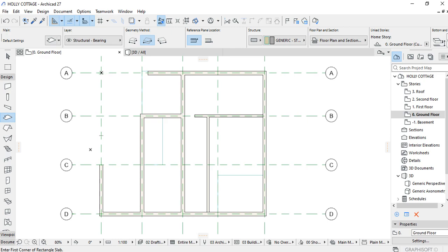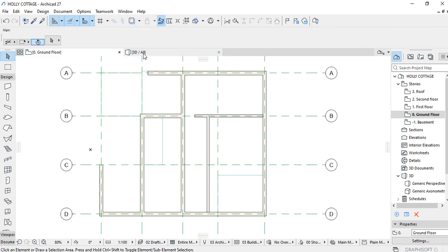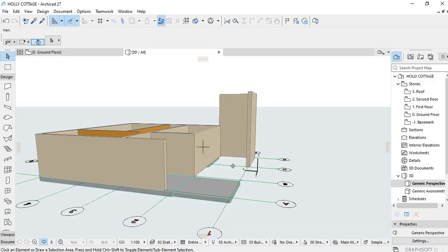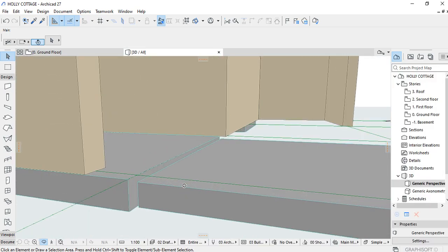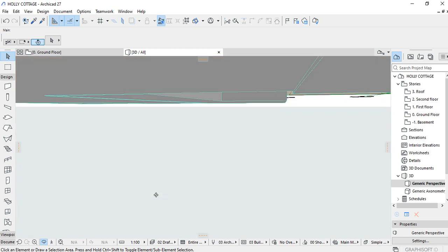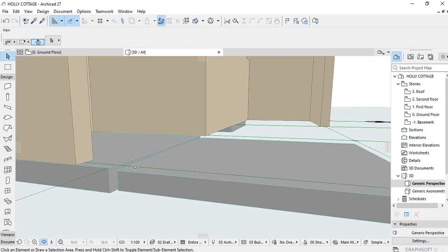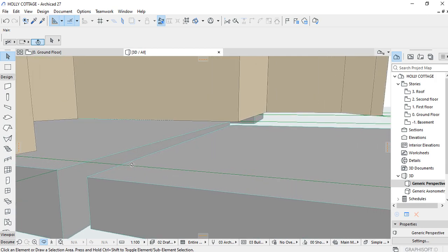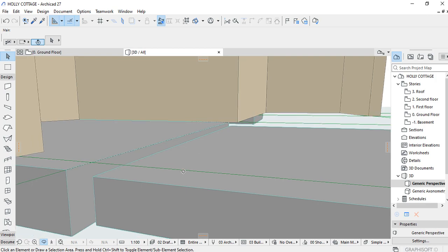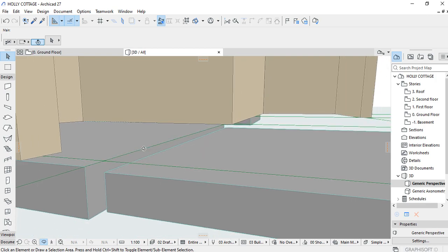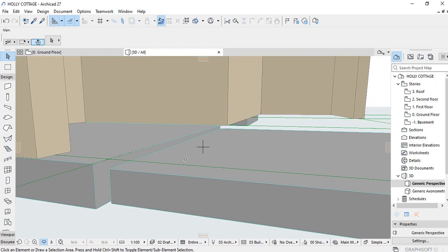So we could select here, then to there. Okay, so it has been inserted. We can go to our 3D view to view it. So here it is. It has been created with an offset of 70 millimeters from the first initial slab. So if you have stepped slabs, you could add them by increasing the offset in the properties.